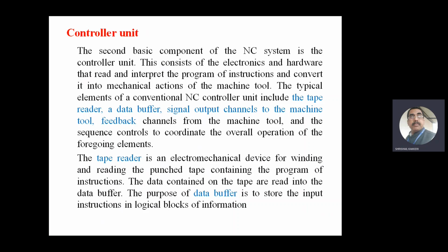29.6 degrees. So, here, the main important function of the controller is that, please understand, for 30-degree rotation, it has been rotated by 29.6 degrees. And this is the error generated, and whether this error is linear, proportional, integral, differential, or PI, the integral proportional differential plus whatever it is, based on that, internally it will be developing some kind of equations. So what happens? For 30-degree rotation, it is rotating by 29.6 degrees.